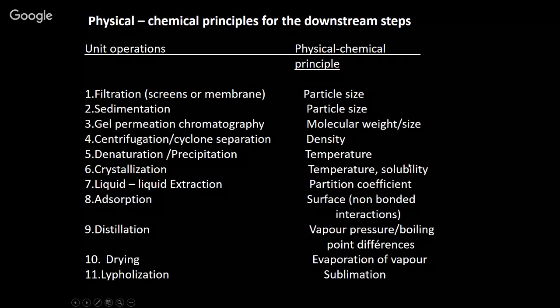Crystallization. Of course, this depends upon the solubility of various solids. Temperature plays a very important role. So you have a saturated solution, you reduce the temperature, so the solution becomes supersaturated, and then the material starts slowly crystallizing, and then it falls down, or settles down as a solid, and the liquid and solid separate out.